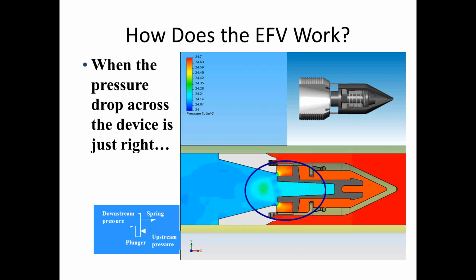on the upstream pressure, then what's going to happen, if you look at this upper square right here, the excess flow valve, it snaps closed. So it reaches a particular signature where those forces flip over and then the valve closes very, very quickly. It's designed to close very quickly once that signature is met.